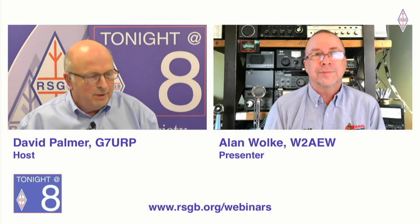So if it's me, I will typically tune for the best return loss, the lowest SWR, to get the best power transfer. That doesn't always mean resonance. Okay, I think that's hopefully helped him as well.